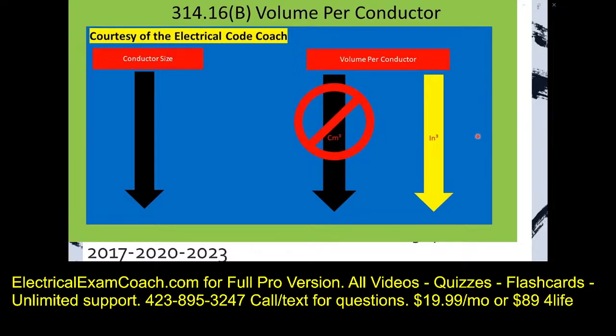this lesson here today. Each box has so many cubic inches that you can fill, and each conductor and device takes up so many cubic inches of that box. Now, let's do some practice questions and get to it.